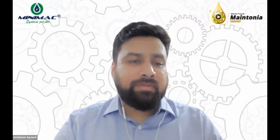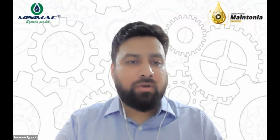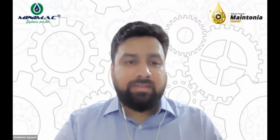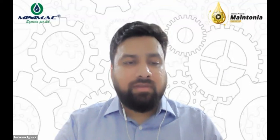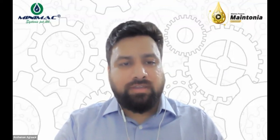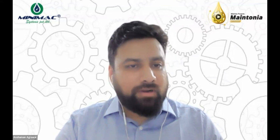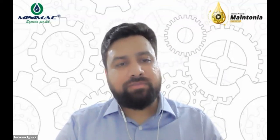Of late, it has been seen that coalescer based technology is replacing the centrifugal technology because of its ease to operate, ease to maintain, less number of spare parts, and less number of headache, of course. So coalescer technology is best when it comes to free water separation. And as I mentioned earlier, low vacuum dehydration is best to remove the dissolved moisture content.